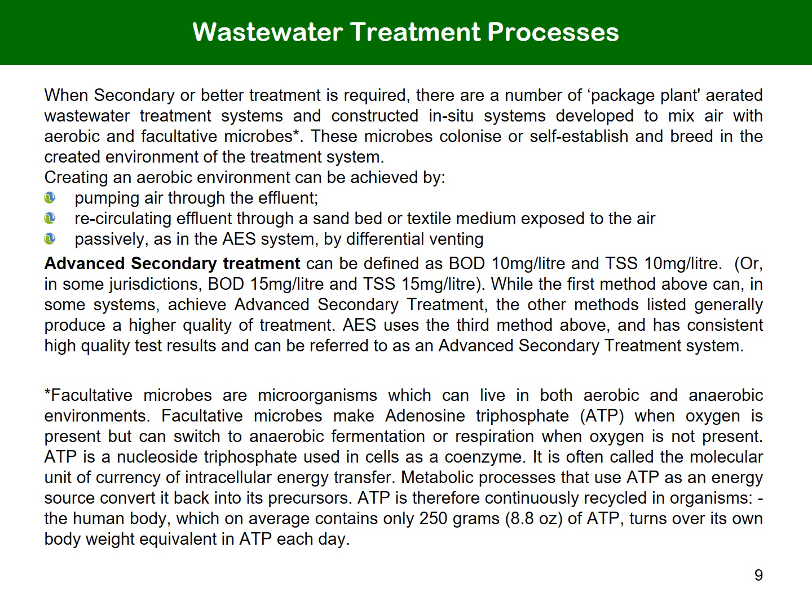Advanced secondary can be defined as BOD of 10 milligrams a litre and TSS of 10 milligrams a litre, or in some jurisdictions 15 milligrams a litre for both. While the first method above can, in some systems, achieve advanced secondary treatment, the other methods listed generally produce a higher quality of treatment. AES uses the third method above and has consistent high-quality test results and can be referred to as an advanced secondary treatment system.